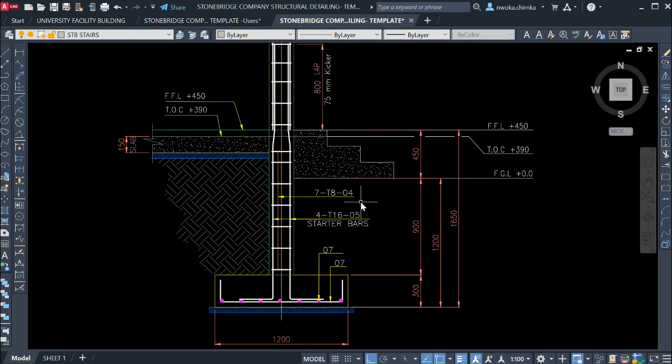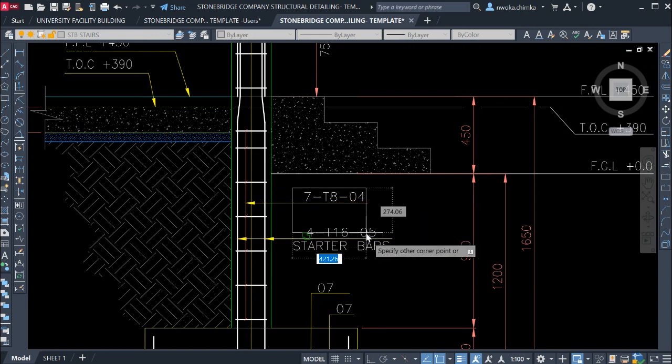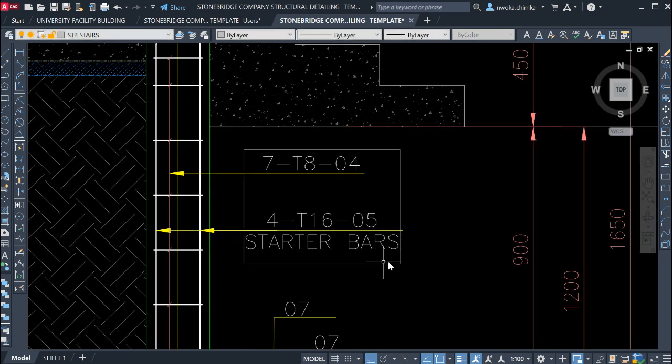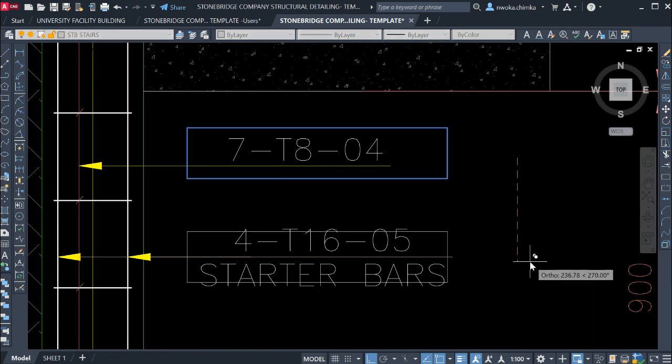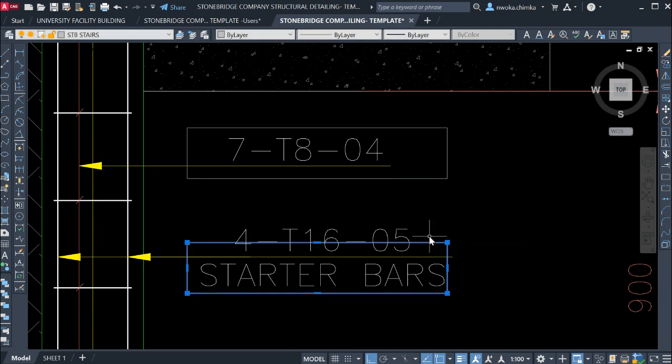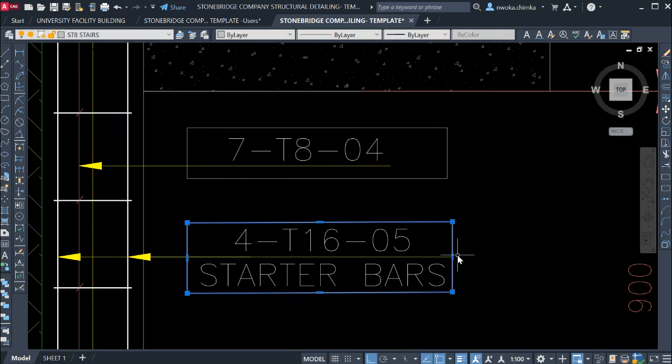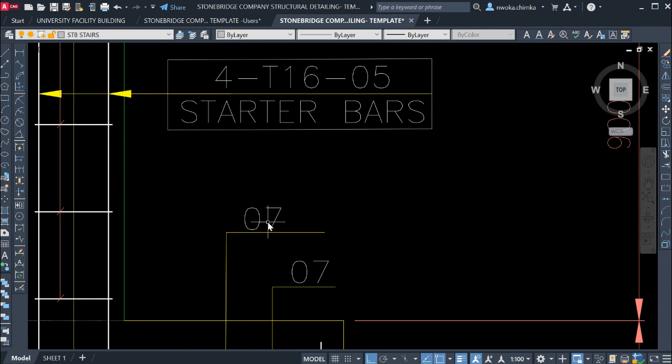So we will also have to show this soil at this other end too. So what I'll do is block this place. I just have to form a block on this other place. I'll form a block around here first and do the same. Let me just stretch this backward a bit, and do the same thing for here. Just show a block here first, then copy this downward again and keep this here, and then copy, change here again and keep it here also, and then keep this here also. Okay, and then what I'll do is also show a block, and I'm blocking this also to hide this text from being hatched.